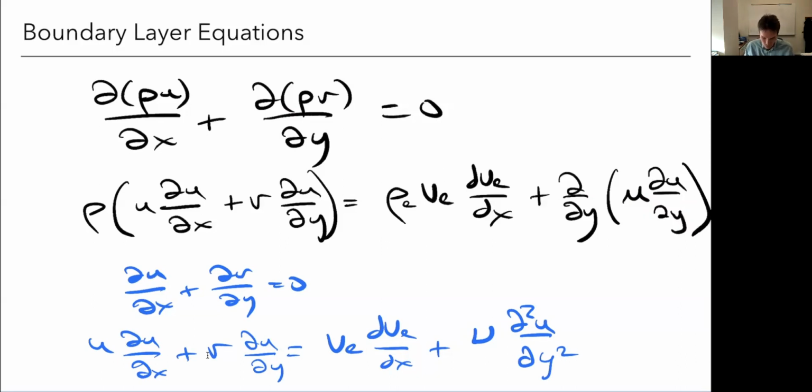And the third equation went away, right? That was that pressure term that we used to simplify this one. So we've taken our Navier-Stokes equations. We've simplified it into this form now, which is easier to use. And the reason for that, well, first of all, there are fewer terms here, so that's nice. But the main reason why it's easier is that the original equation is what we'd call an elliptic PDE.